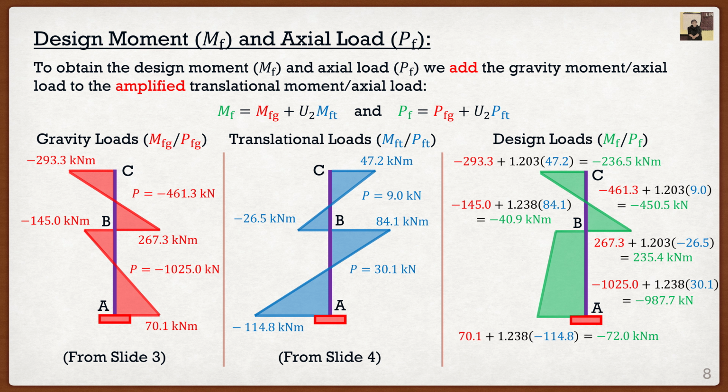So this is exactly how you determine those design moments. Again, we do a gravity load analysis to determine the moment and axial load there. We do a translational analysis to determine the moment and axial load for there. And then finally, we add them together with some amplification to get our final design loads.